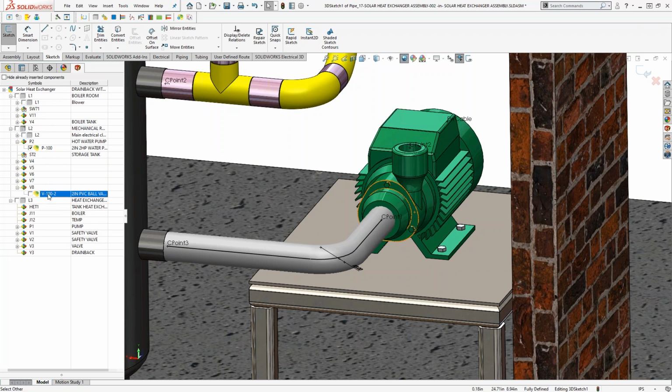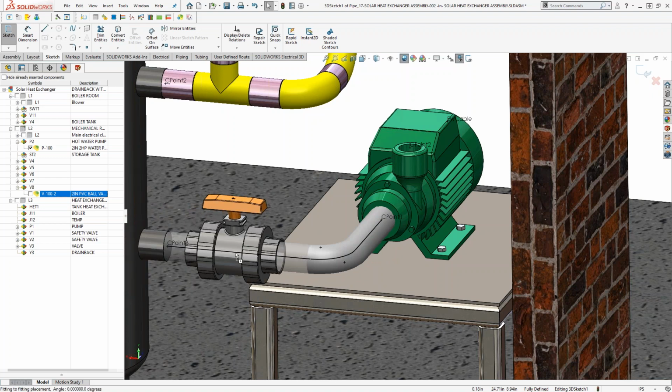Now I'm still in the subassembly of this pipe. Find this valve. Now I could add it anywhere along this path. Obviously this side doesn't really make a lot of sense. I probably want to add it over here. I can always add some dimensioning to it as necessary so that we get the same for every single pipe that we get. Let your OCD sink in on that one for a little bit. And now we have our small pipe section here.